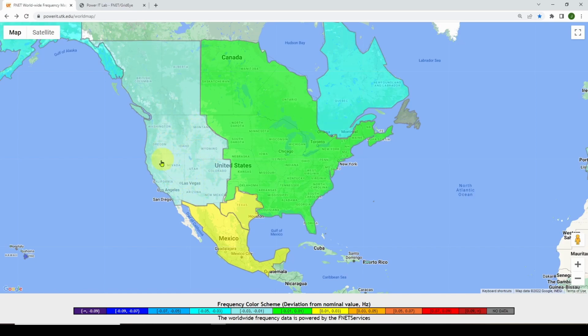So, for example, if an area of Montana suddenly lost some generation and needed some power, since it's tied in this grid, it could say, hey, I need some power over here. Give me some power from Washington, and it's a lot more reliable. You don't have to rely on just your own generation, and if you run out of generation, you have to shut off all the power. So it's more reliable. Now, the downside is, for example, let's say there was a big problem in Los Angeles, it got overloaded and nobody else could give it enough power, the entire grid could go down. So, there's good sides and there's bad sides to it, as with anything in the real world. You have benefits and you have disadvantages.